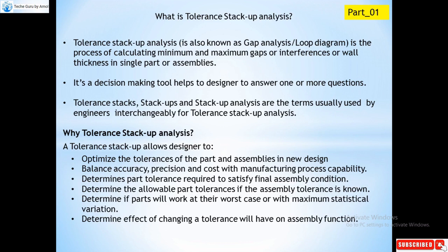It determines the part tolerance required to satisfy the final assembly condition, determines the allowable part tolerances if the assembly tolerance is known, determines if parts will work at their worst case or with maximum statistical variation, and determines the effect that changing a tolerance will have on assembly function.